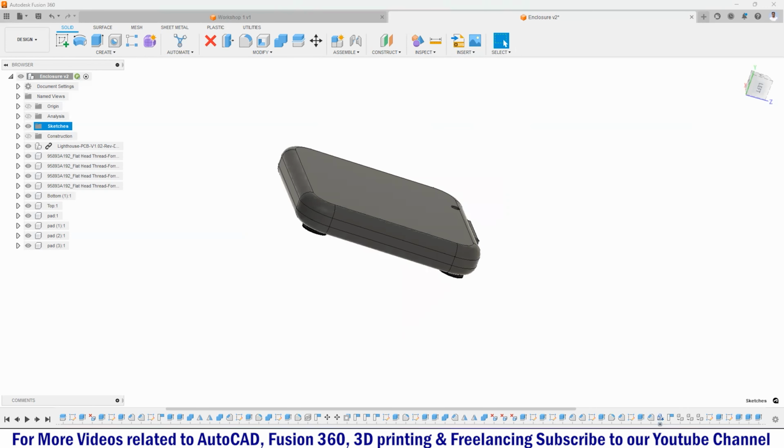Now, the next stuff, guys. After this document settings, after this units branch, here you will be able to see another branch named views. If I expand this named views, here you can see the top, front, right, and home, 4 default views. From this, we can navigate across our 3D model. If I double click on the top, here you can see my ViewCube just got rotated and is showing me the view from the top. If I double click on the right, the view got updated. So this way you can navigate across your 3D model using these named views.